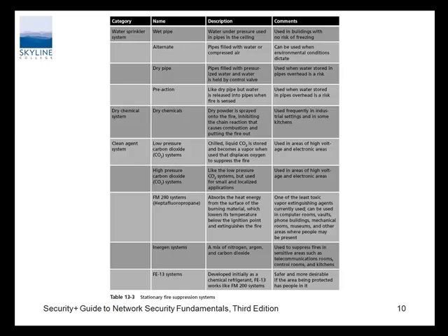In here, and I think these are actually wet pipe, probably what you would want is a dry pipe. Also, one of the issues with wet pipe is unless you drain it every once in a while, you know how nasty that water gets? So not only are you going to have the water damage from the initial sprinkling, you're going to have all the other stuff that comes out. And what about stopping up the sprinkler heads?